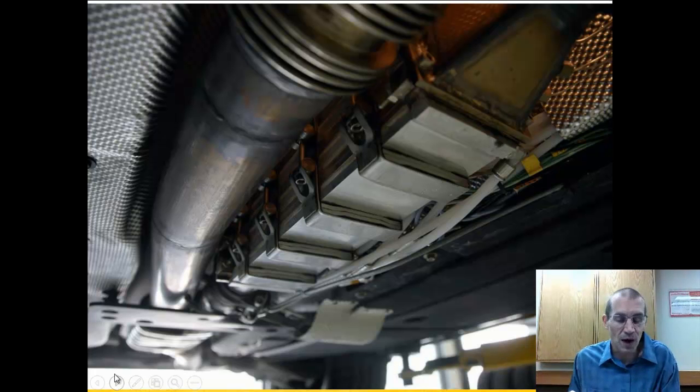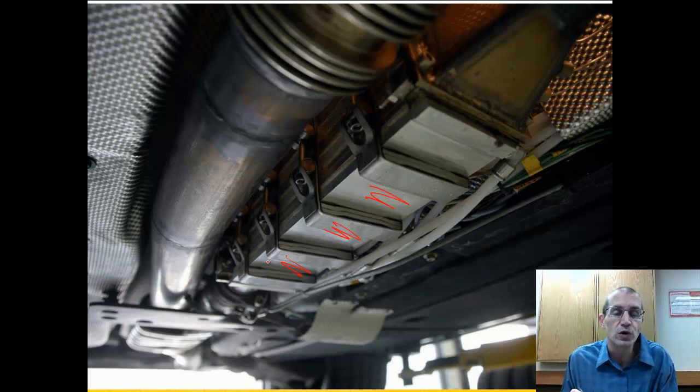Well, here's where thermoelectric generators actually are being tested right now. And this is the underside of a BMW vehicle. And it's attached to the exhaust manifold. And these are a series of TEG units right down underneath here. And what they're doing is supplying auxiliary power to the car. So it's taking what would normally be considered waste heat, which is the heat coming off of your engine out the exhaust pipe, and turning it into some additional electric work. TEGs are sort of cutting edge technology. They're not really commercially viable yet, but there's a lot of research going on with them.